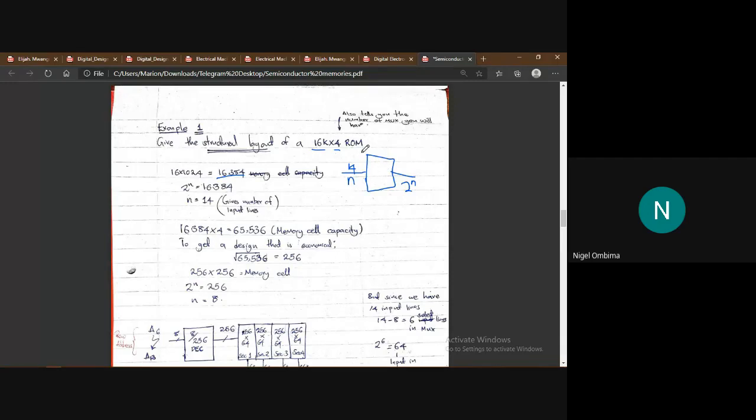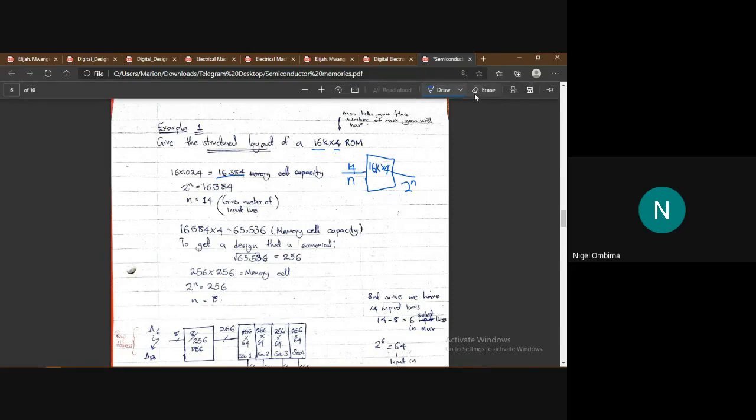And a decoder normally is inside a ROM chip. So let's assume these are 16K by 4 ROM. So the decoder is in there. So the number of input lines will be 14. Then the number of outputs should be, we'll ignore this one, which I wrote at the start. Data out now should be 4. This is a 16K by 4 ROM.